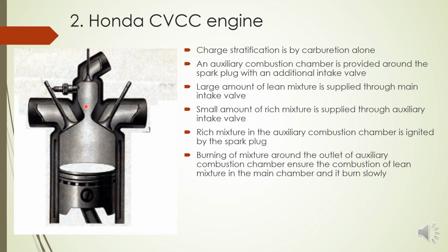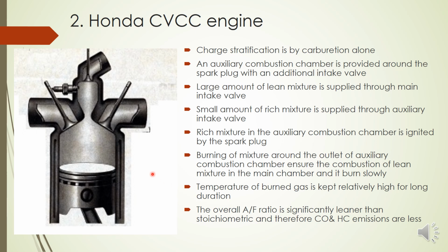It happens in two stages, and the temperature is kept relatively high for a long duration, and overall the mixture will be lean. Here we are using rich, here we are using lean, but taking the overall mixture strength, it will be leaner than a normal petrol engine, and therefore we have the advantage of less carbon monoxide, fewer hydrocarbons, etc. We are using a lean mixture. So this is the second method of charge stratification by carburation alone.